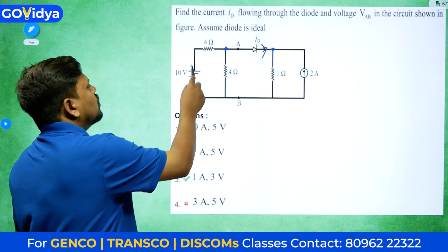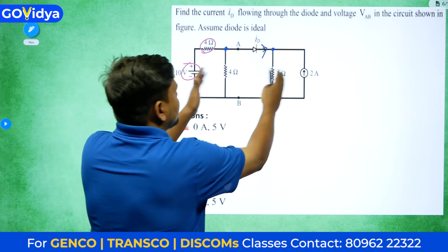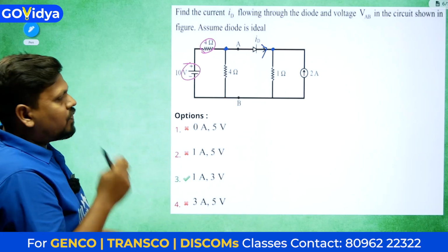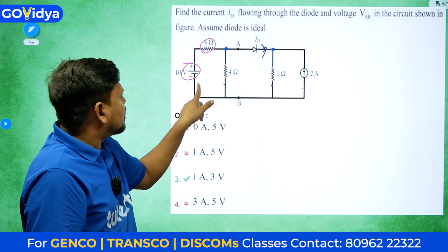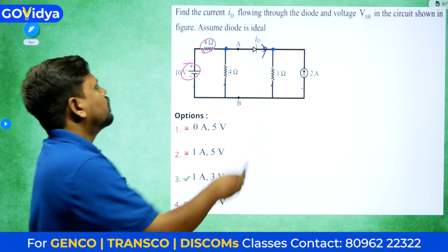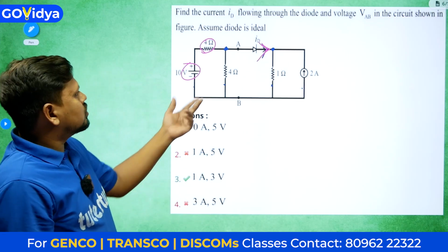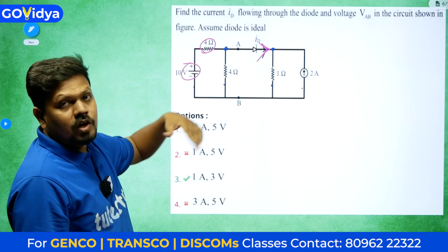So what you will do: voltage source in series with resistance. We need to know these elements we can change to anything, there is no problem. If they were asking about the current here or here, we could not change the network. But now we need the current here, so just directly follow. We can eliminate all these things by following certain rules.